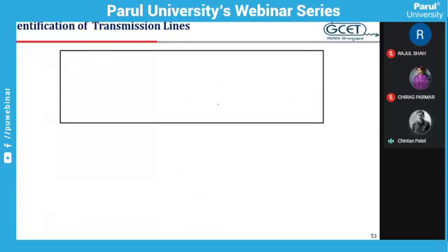Now, how can we identify the voltage level of a transmission line? One method we have already discussed is counting the number of discs. But if it is a silicon rubber insulator or composite insulator, then it is difficult to count the number of discs. Or if the transmission line tower is located at a very distant place, then also it is not possible to count the exact number of discs. So there are certain methods to identify the transmission line voltage levels. The first method, already discussed so I'm not repeating, is based on the number of insulator discs in the string.